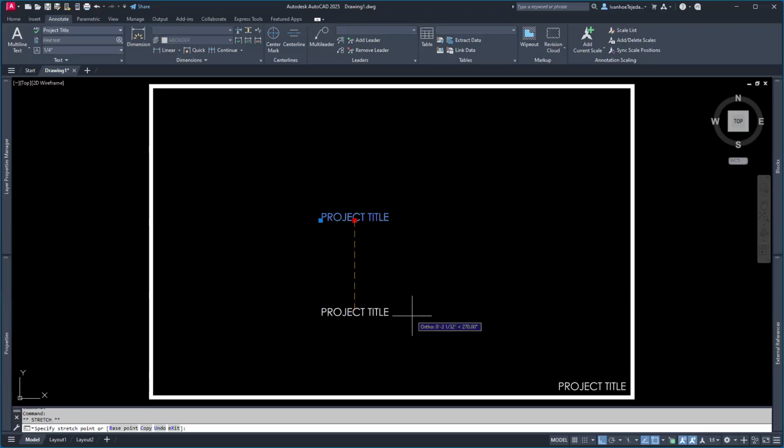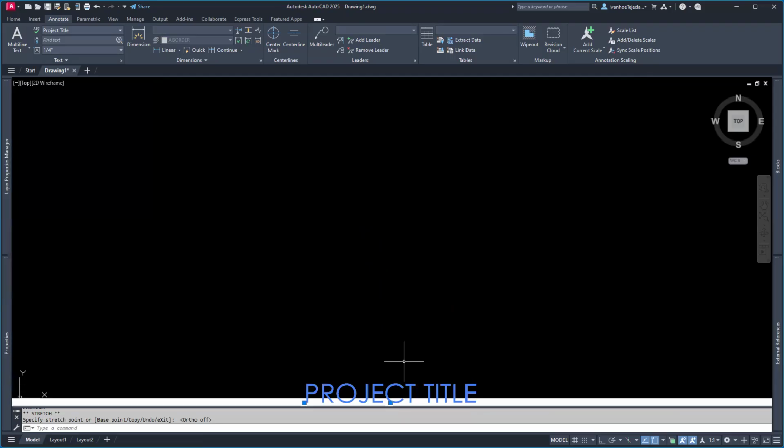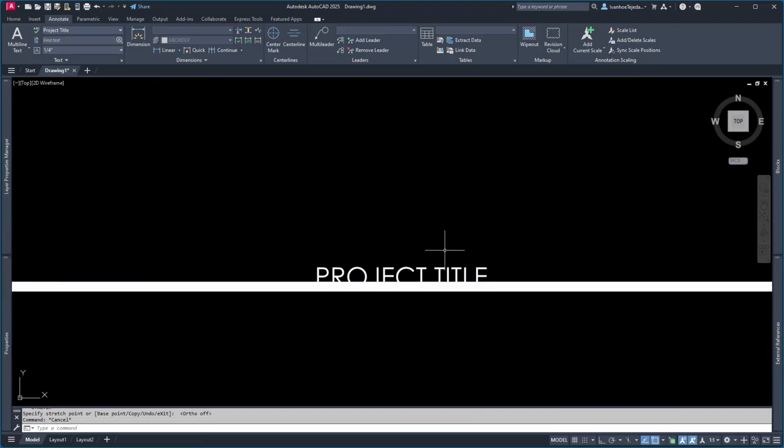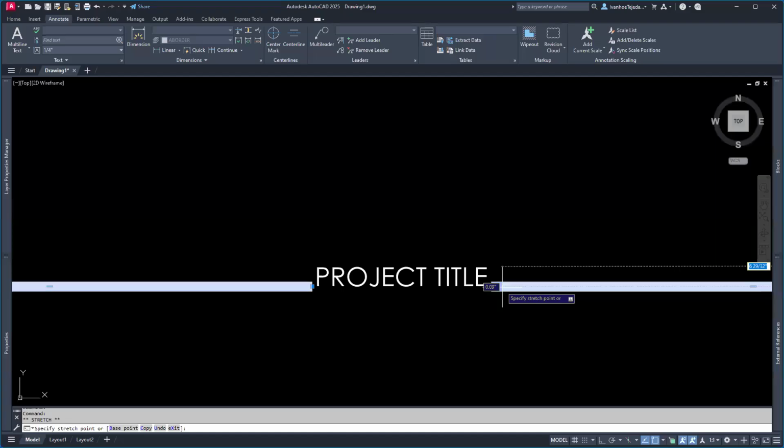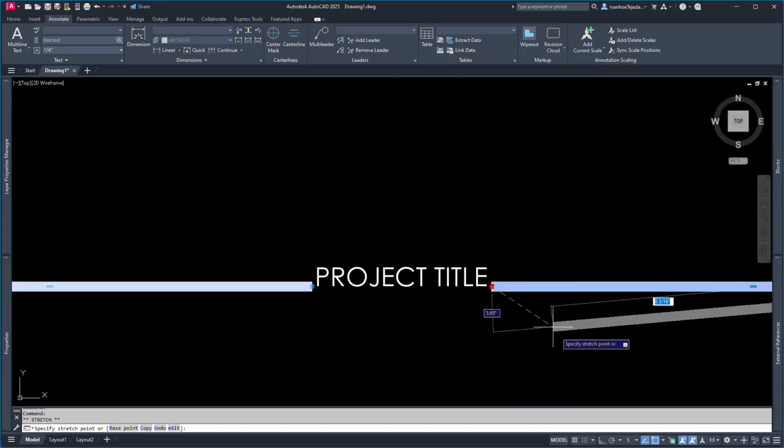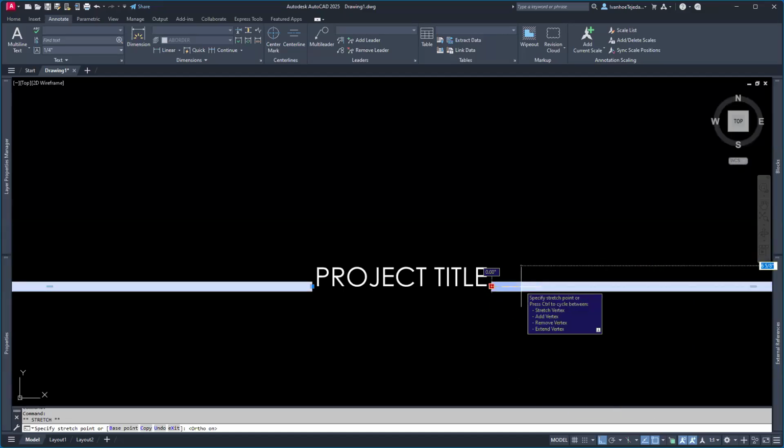So I can take this, move it over. Let's turn off ortho, place it somewhere here, give it a click. And let's see if I can trim with single line text. So if I type tr, enter, I click right here, it'll work, and enter. So same applies. And if that feels a little too tight for you, just use the grips, grip it and just move it over whatever distance you want, turn on ortho. Yeah, it's up to you.